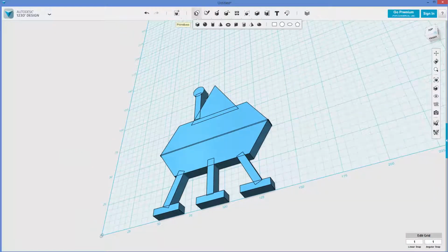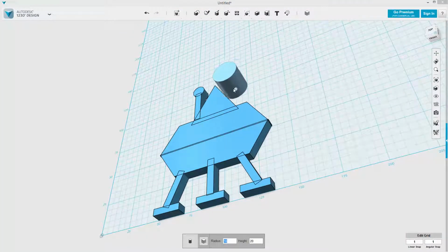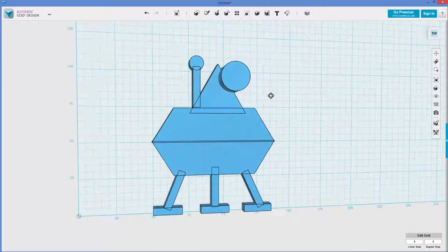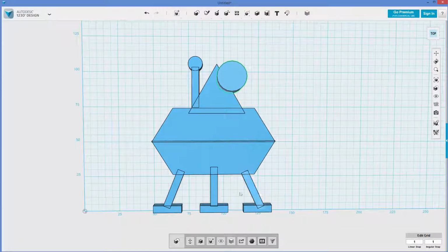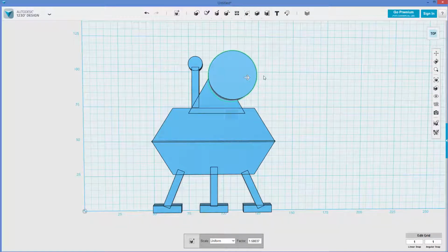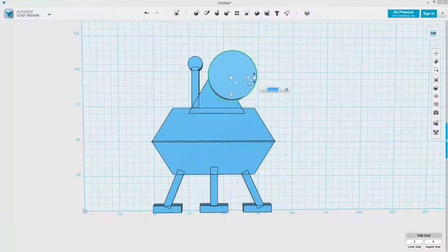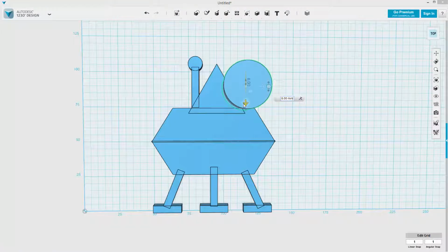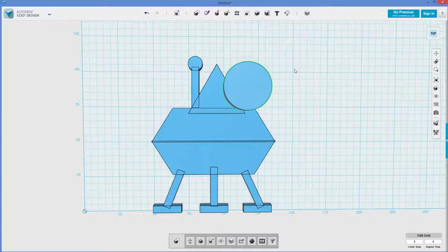All right, so this is a bigger cylinder, and we will plop it right here. Is that a good size? I think I'm going to scale it up a bit and move it with the move command. Something like this, I guess. Hit enter. I'm going to hit the D key to drop.